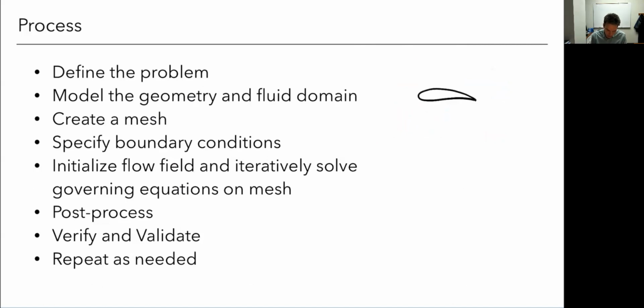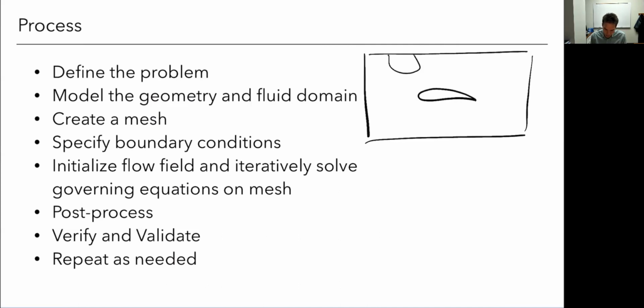So sometimes we'll define the size I want around here in the far field relative to some reference area. In Star-CCM+, that is called a base size. And maybe I'll define things in the near body relative to some size that I want, and kind of a transition rate. So I can tie everything into a number, and maybe I'll define a size in my wake, for example, if I'm trying to resolve that. And I'll modify this. And this will be a good way to see convergence.